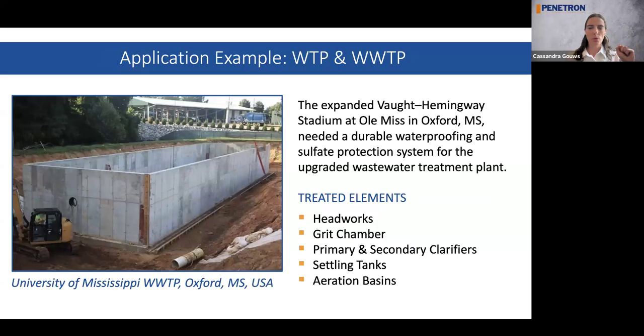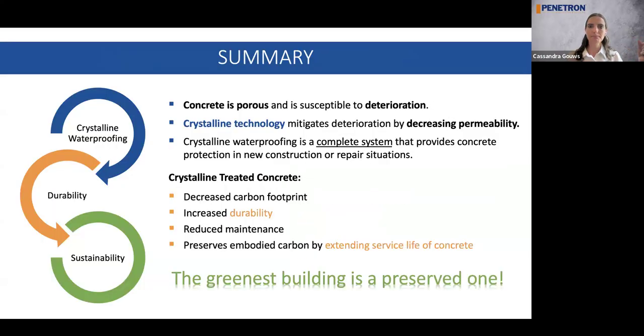And then lastly, the water treatment plants or wastewater treatment plants. So whether it's the containment structures like the headworks, the grit chambers, primary, secondary clarifiers, settling tanks, aeration basins, all of those would be good applications, not only from a waterproofing point of view, but for durability. So protection against all those chemicals they use to treat the water, as well as the sulfates.